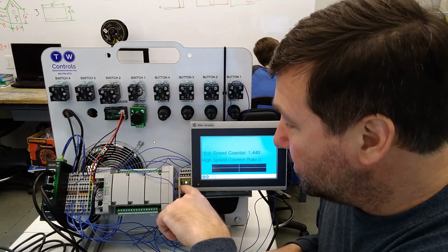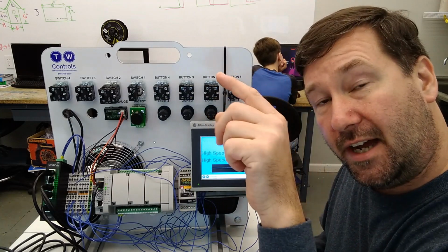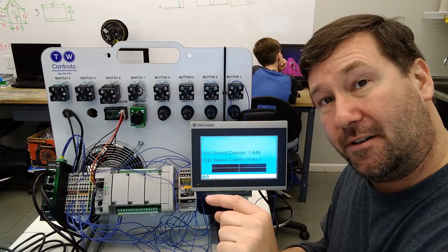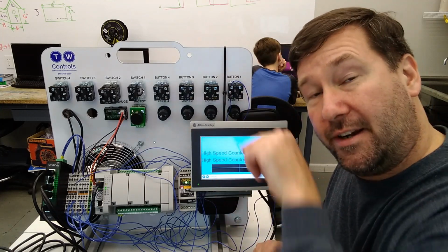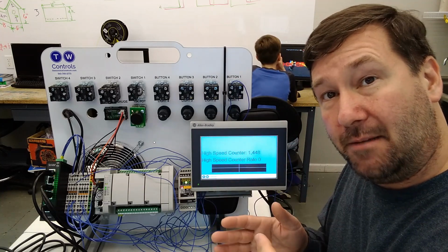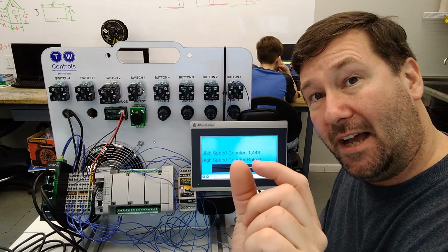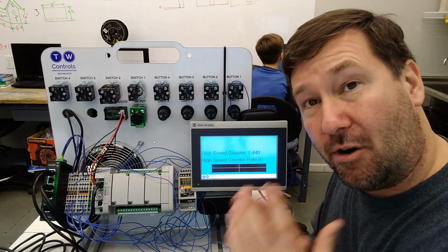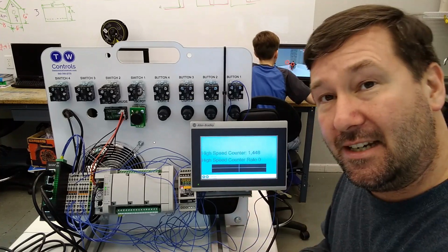And 100 Hertz means that we're going to be turning on 100 times in a second and off 100 times in a second, which is going to be a total of 200 transitions. So you have 1,000 milliseconds, you divide it by 200. That means our transitions are 5 milliseconds wide, but our filters are 8 milliseconds wide. And so they're not going to ever catch anything.